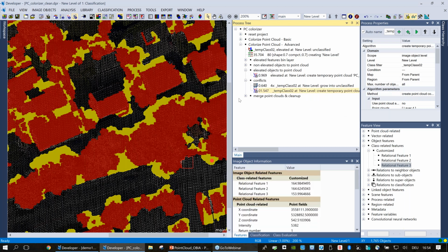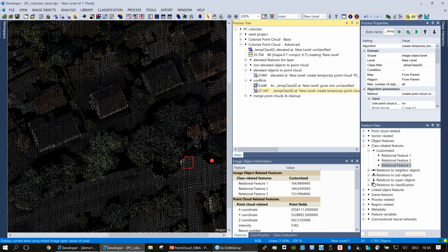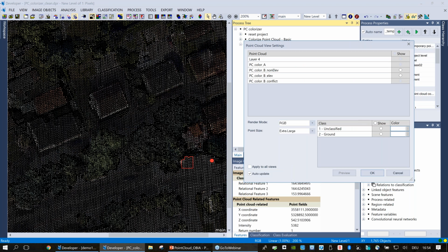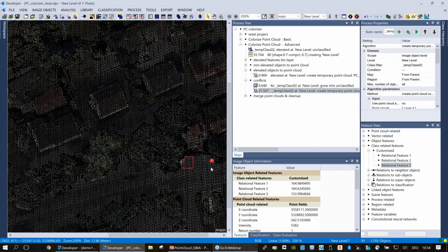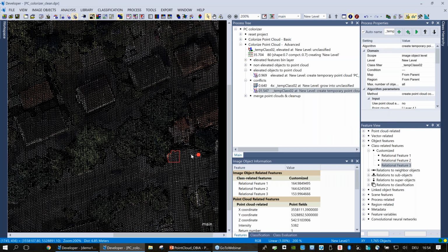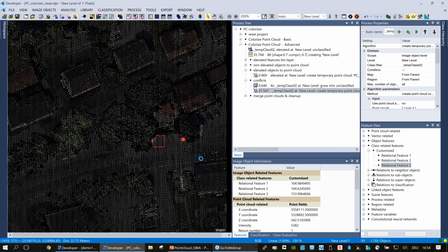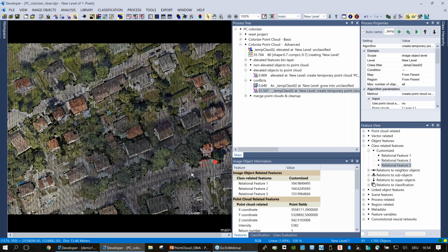And now we're going to execute this. Turn off the classification. And I can come back in. I see this third layer is now available. And I see now this has been added. Now I have all 3 of these layers, all my points are essentially back together again. And you can see some slight differences here because we used a sort of broader stroked chessboard segmentation, if you will. Remember, it was set to I think about 50. So you can optimize this by changing the segmentation parameters.